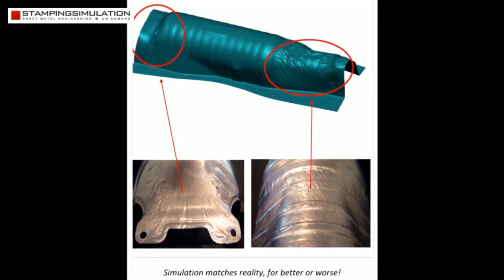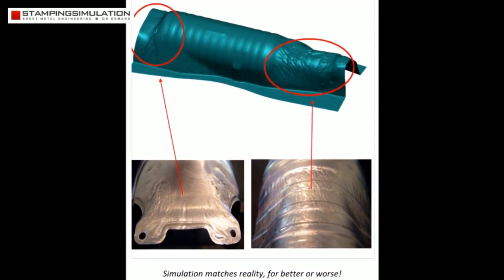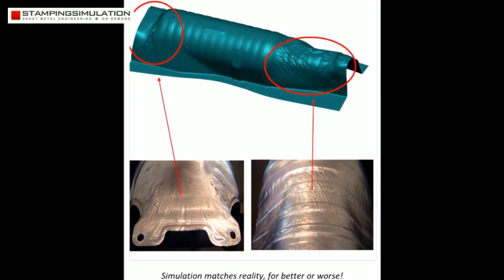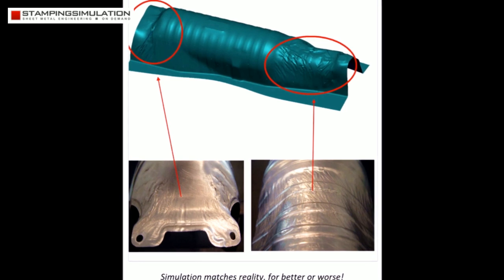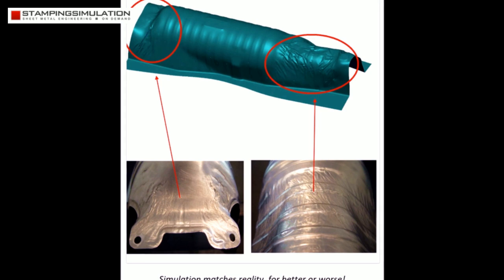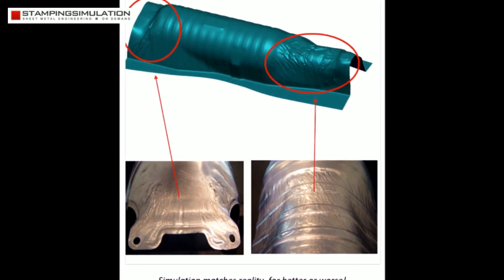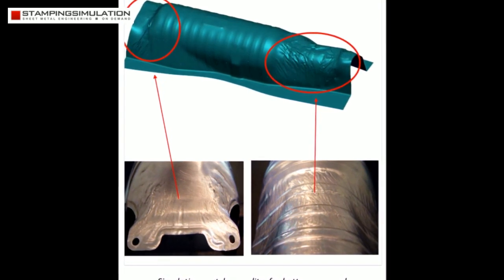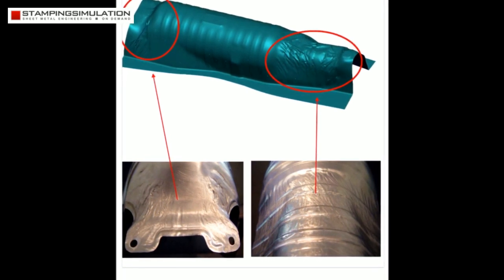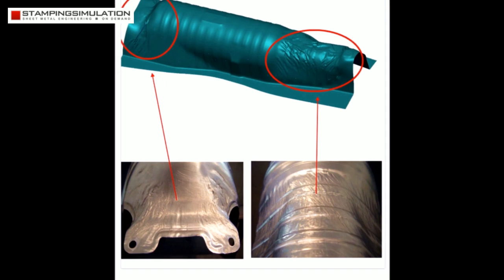2. Tooling geometry used in simulation must match tooling manufactured exactly. A 3D tool design simulated and validated in simulation must be continued without change to the tool room floor. Any changes to the tooling process steps or shapes must be revalidated in simulation to avoid an unexpected outcome in reality. For this reason, stamping simulation provides final validation for every job.